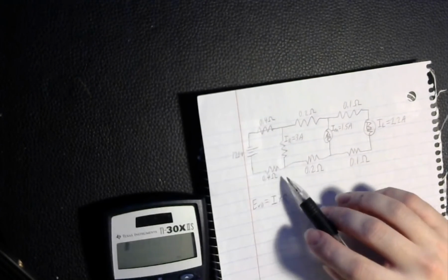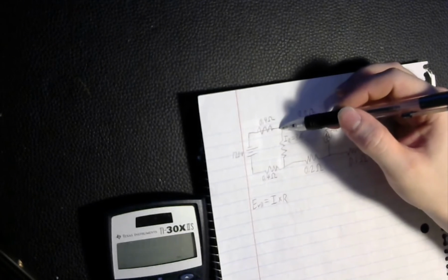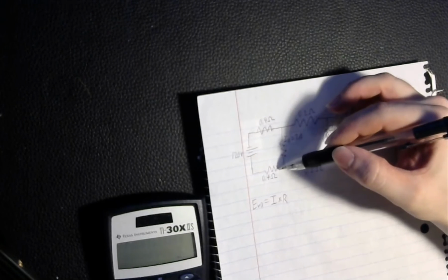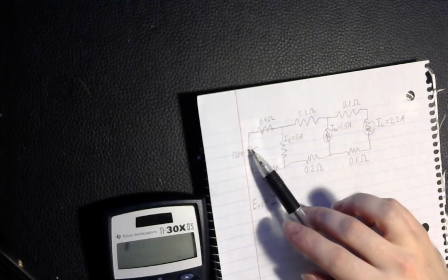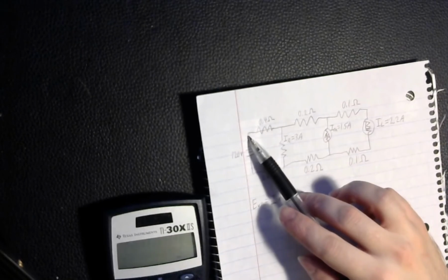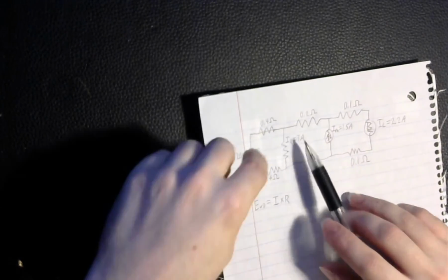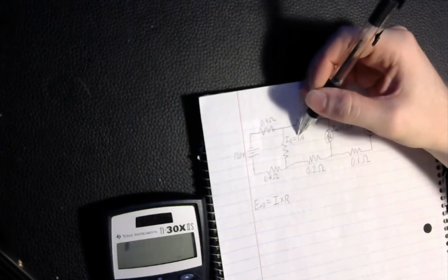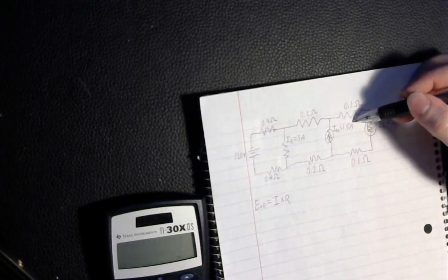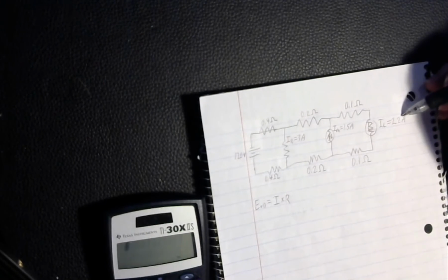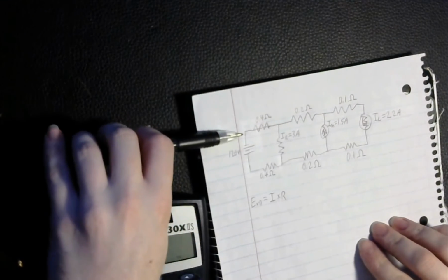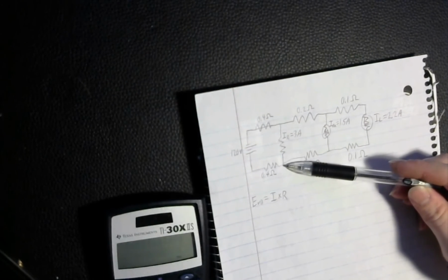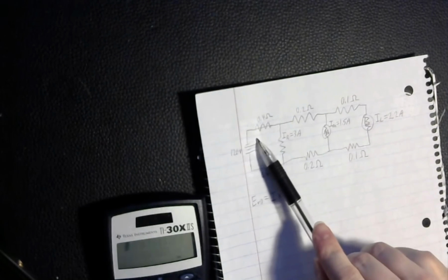So now you've got that. Now it is correct. You've got 3 amps going down across here, but the total amperage, you have to add all three of them together. Basically the amount of amperage that's entering this node here is 3 amps, but there's also the additional 1.5 amps here and the 2.2 amps here that are entering into this node, and then that same amount exiting back out from this node here, going back to your power source.